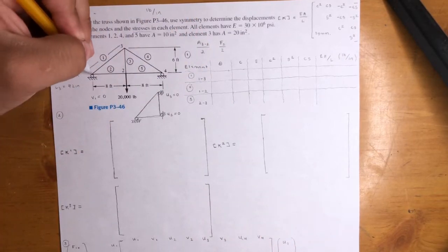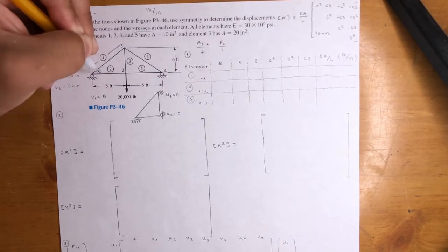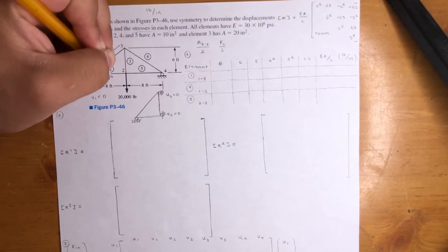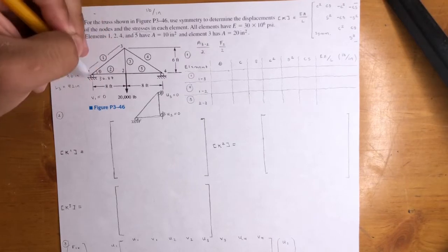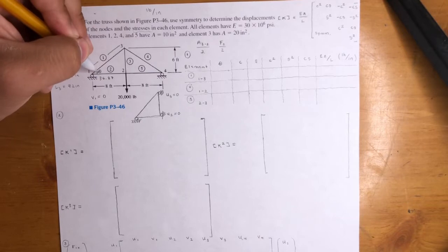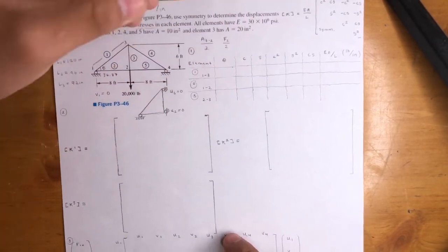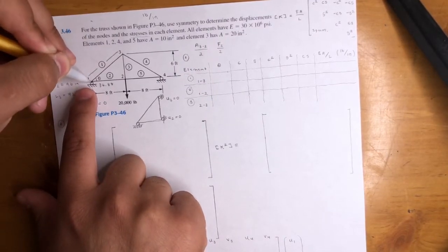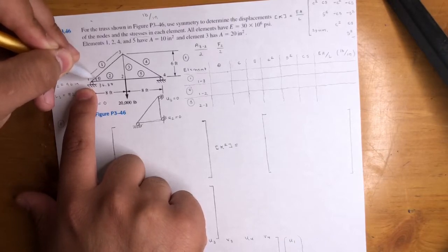So we're going from 1 to 3, right? This is a 3, 4, 5 triangle. So that means this theta right here is 36.87. That's just trigonometry, right? You could use tangent, sine, cosine. You know the lengths. You could get that angle. You could get this one too, okay? So this angle right here is 36.87. And so that's the one I'm gonna use, right? Because I'm putting my axis at node 1. So the positive y, positive x. This beam goes up this angle right here. So that's why I'm using